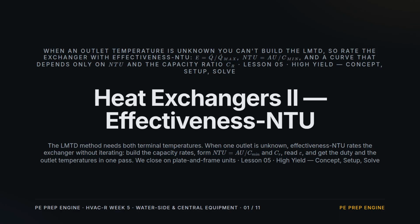Week 5, Lesson 5, Heat Exchangers Part 2, the Effectiveness-NTU method. Last lesson used LMTD, which needs both hot and cold terminal temperatures. The moment an outlet temperature is unknown, that method forces you to iterate. Effectiveness-NTU avoids it. Build the capacity rates, form NTU and the capacity ratio. Read effectiveness off a single curve, and recover the heat duty and both outlet temperatures in one pass. We finish on plate and frame exchangers.